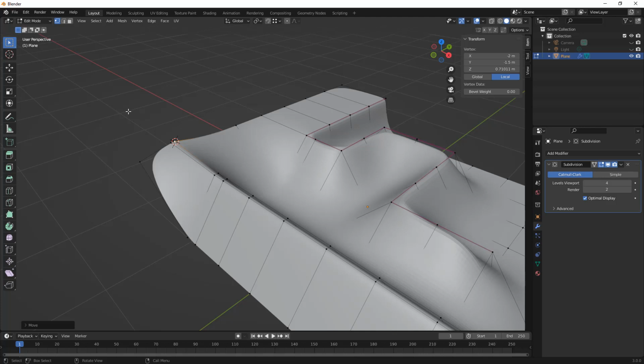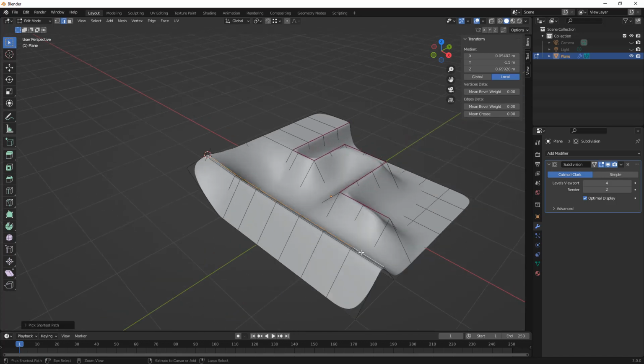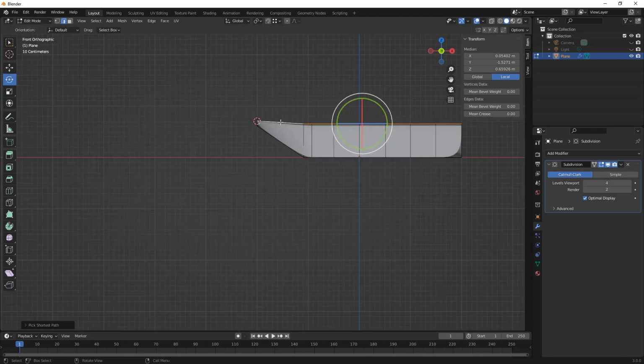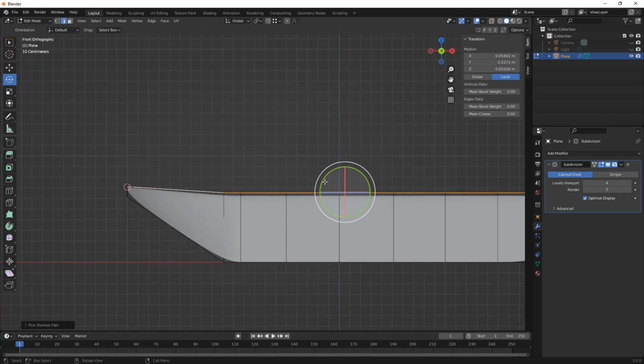If you're just trying to insert an object using the 3D cursor, then usually Shift and right click will get you pretty close. If you want a specific pivot point, however, then making sure that you place it snap to something can help. Now let's go ahead and again, Control Select. We're going to go all the way to the end here and all the way back. We're going to go to our rotation. This time we're going to go to the side. We're going to just pivot this down. And now what we want to do is we want to rotate based on our 3D cursor.